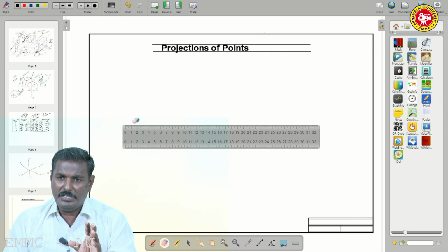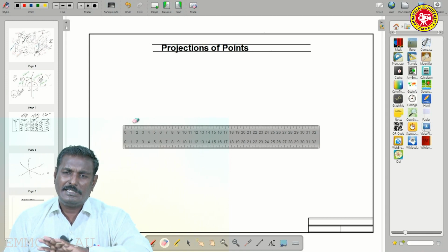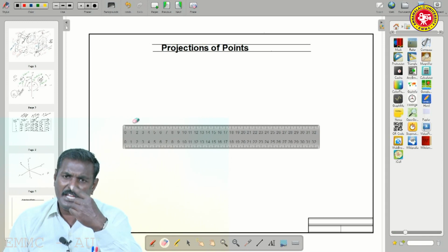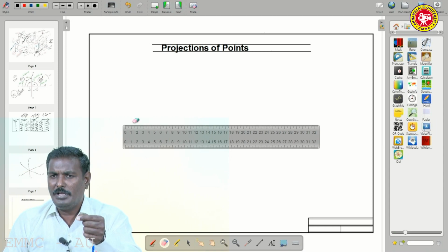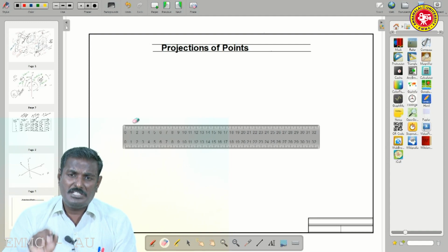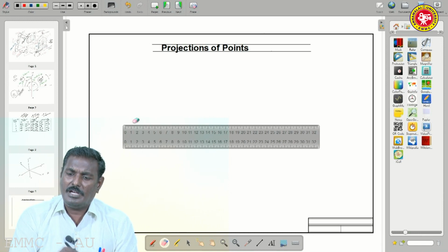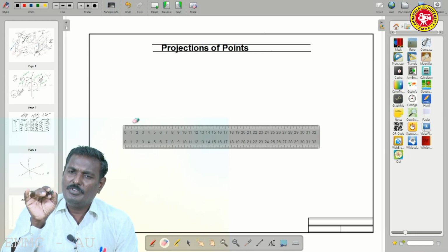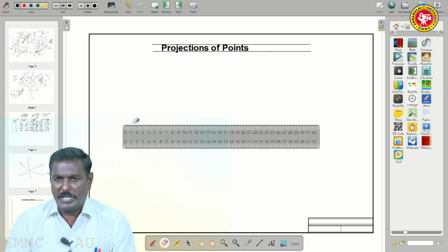One is the 2H pencil for initial work, all construction lines and imaginary lines. After confirming your shape, trace again perfectly with a sharp H pencil, slightly impressing, not highly. For lettering, writing letters, words and statements, use an HB pencil. Here also don't press, write the lettering with some darkness.